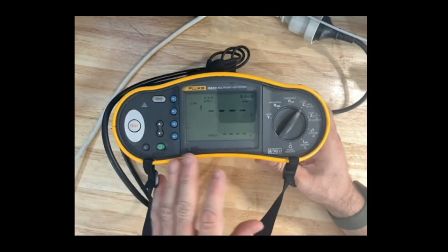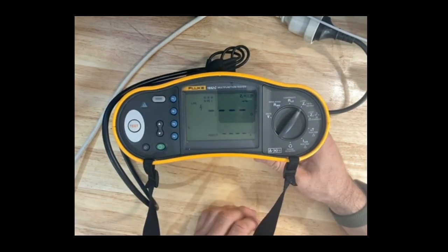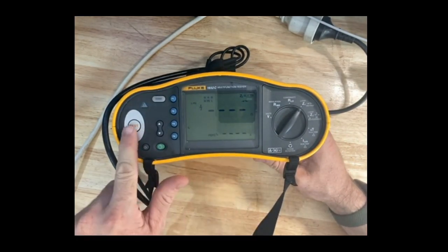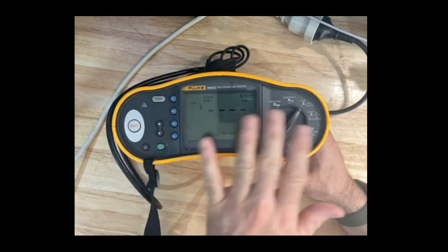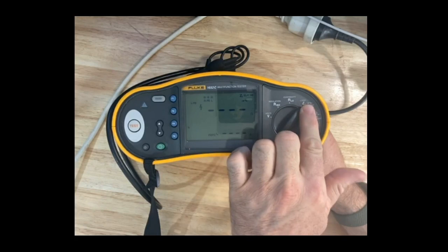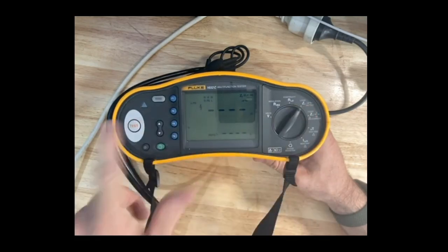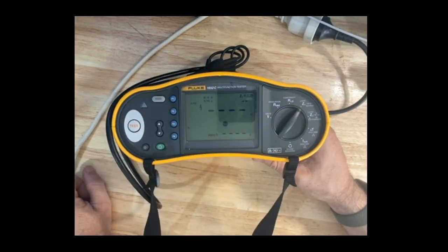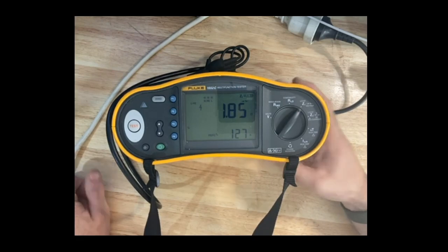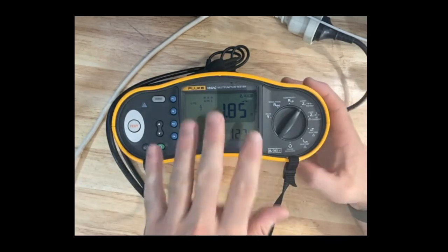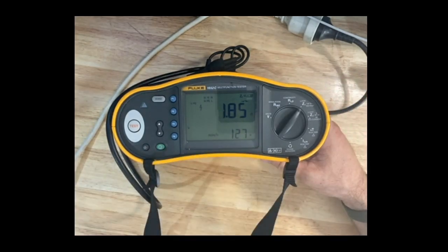And that's all I need to do, really. The next thing I need to do is push the button, and the magic test machine does the job for me. So I've got test button on the left-hand side here. You may have a meter that looks different to this, but it should have more or less the same functions. It'll have a loop function if you're doing loop testing, and it'll have a test button. And there we go. Push the test button, and we'll see what happens. So it's currently running a small current through that entire loop. It'll measure what that current is, and then the machine will be able to work out what the resistance is.